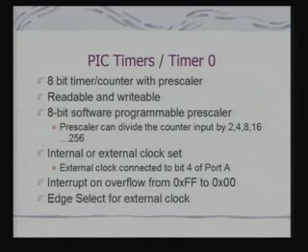So effectively I'm increasing the range, and the time period, over which the timer can really count. These timers are readable and writable, so I can read the current count as well as write to modify it.